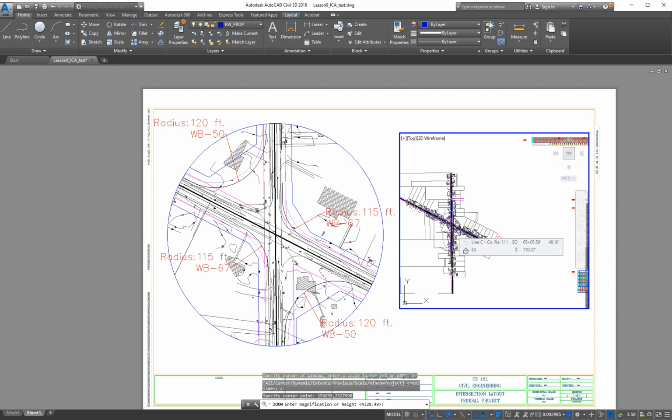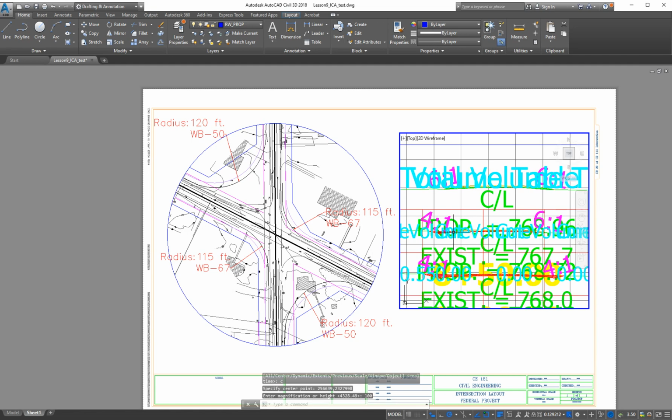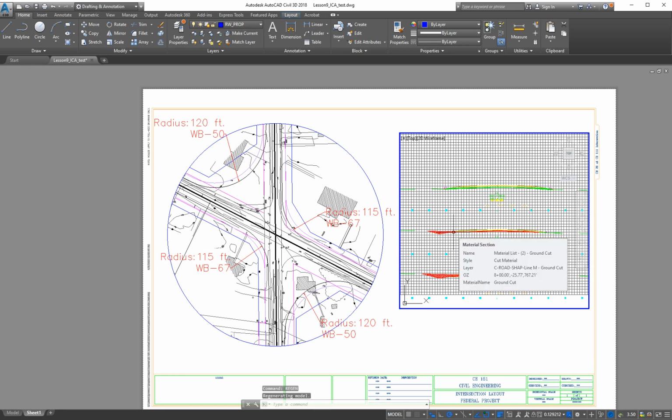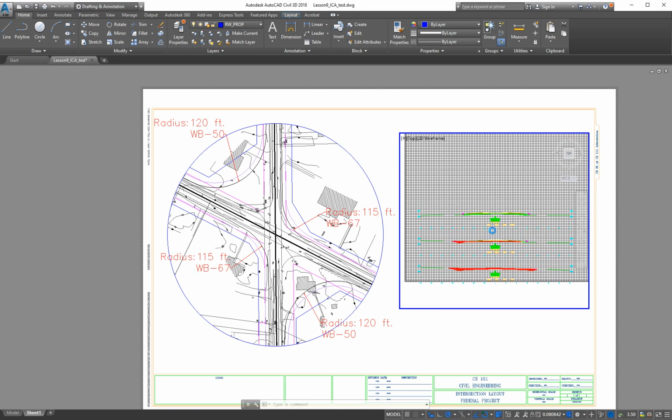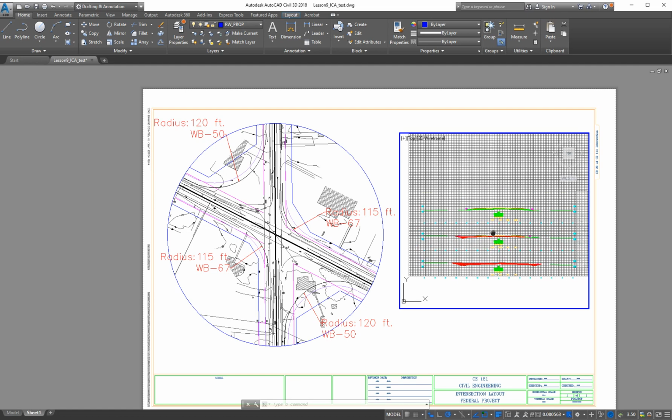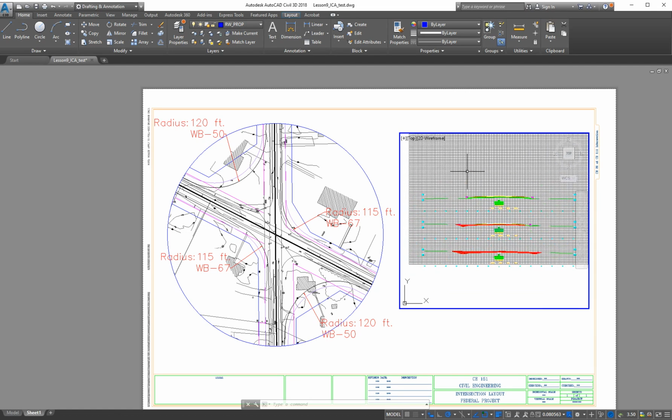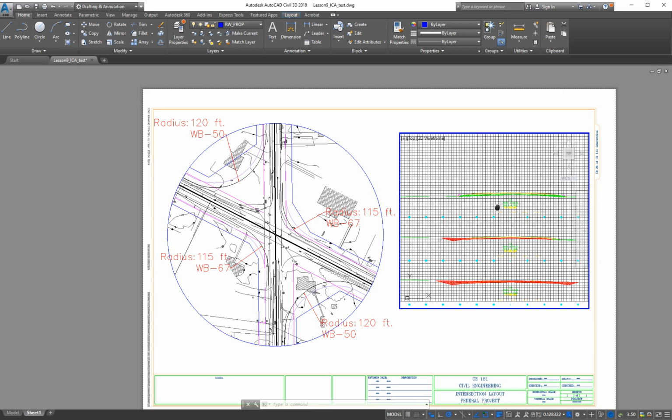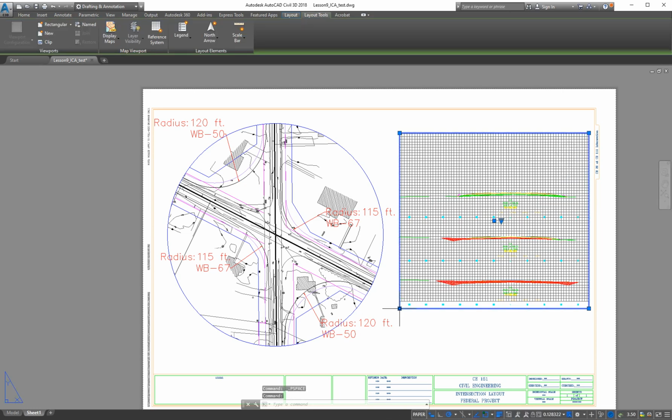What's my magnification level? Let's go 100. Oh, that looks awful. Okay, regen. Okay. That's my cross section, and that's about what it's supposed to look like. All right. Not too bad. You can zoom back out a little bit. I like it more like this. So there's my cross section there. It's not terrible. All right, if I go back to paper space, it locks that.